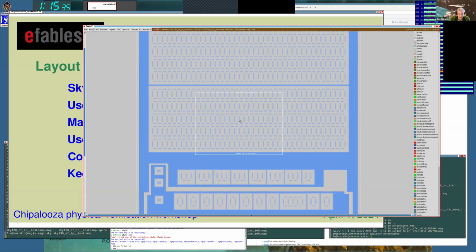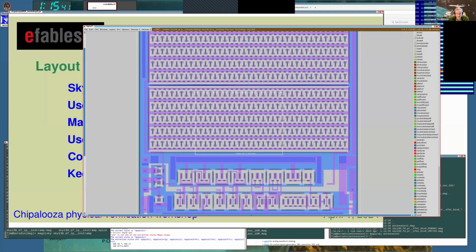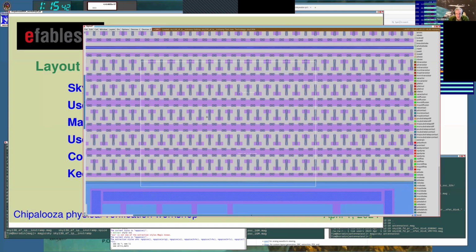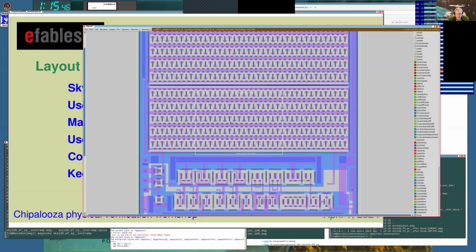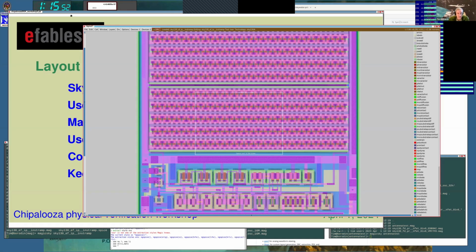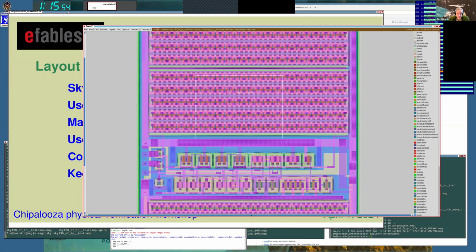So if I add to that the local interconnect and metal 1, you can see I have immediately gone up to metal 1. In fact, in the top, I'm doing most of my routing in metal 2. And that's because local interconnect is highly resistive. If there's something that you would never want to route in poly, then you probably never want to route it in local interconnect either.